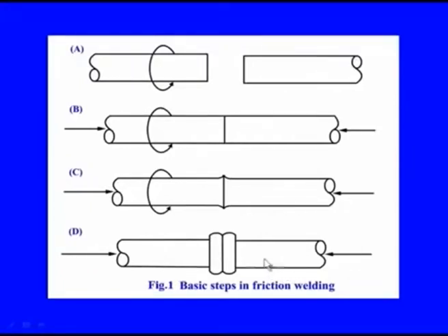Here some issues could be how to maintain the axial similarity. Alignment is a problem here. So, one has to be very careful to make them aligned with the other body, particularly since one body will be under movement or rotation. Therefore, keeping the alignment can be a critical issue.